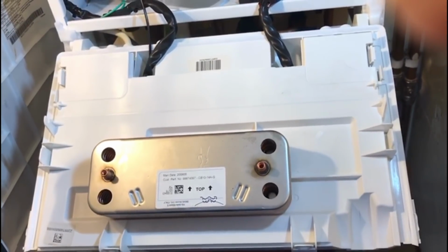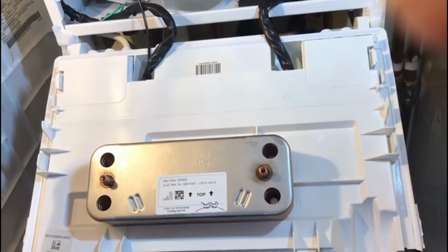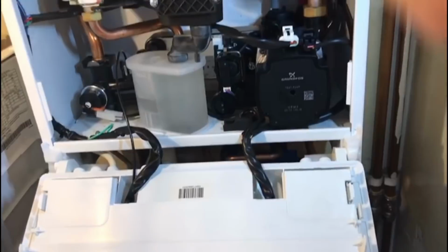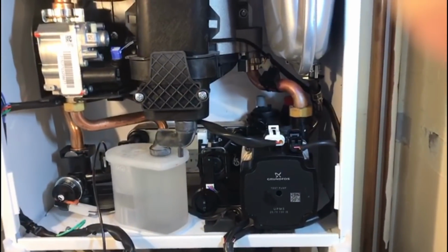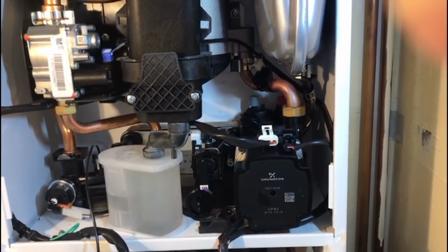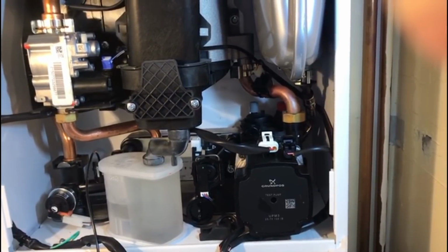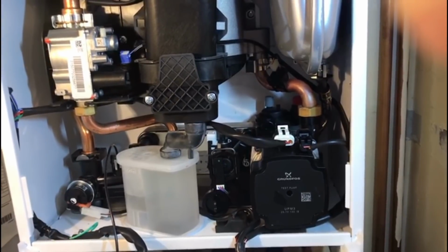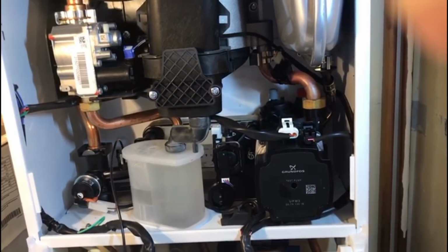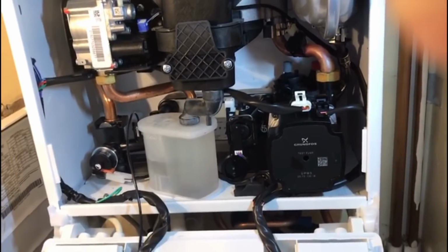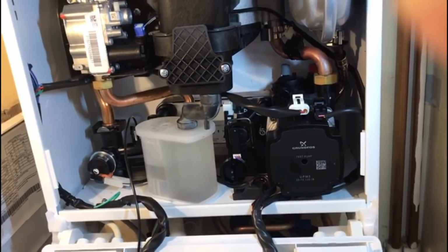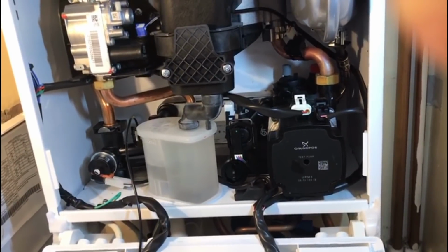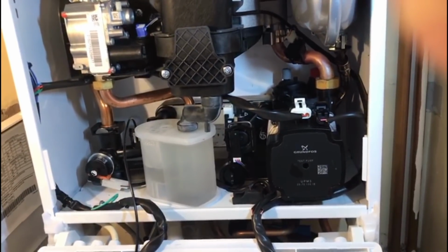5 minutes in comparison to say half an hour or 45 minutes is a big difference. When you've drained the boiler, removed the plate heat exchanger, or even replaced it, filled and vented the boiler, only to find you still have the same issue, I think it's well worth doing these tests. You may also have to charge the customer for time that you've spent and unnecessary parts replacement, so it's worth doing these tests for 5 minutes.